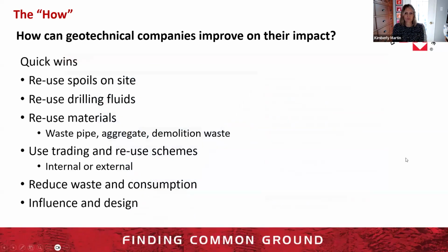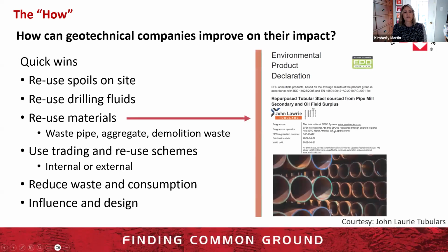Some quick wins for the circular economy are reusing spoils on site, reusing drilling fluids for as long as possible, reusing materials, again, something that may also reduce carbon, using trading or reuse schemes, which could be internal, like moving excess pipe one project may have bought to another project instead of ordering new, or external, which I hear in Europe, there are marketplaces to help reuse material, especially near where it's already located.